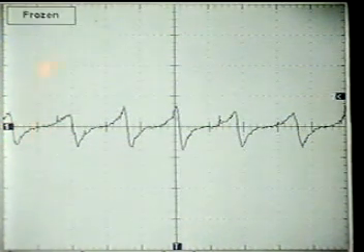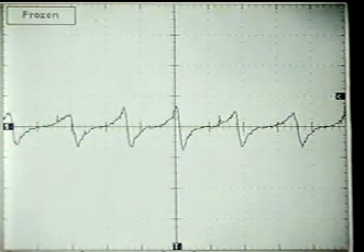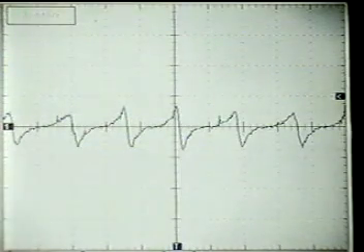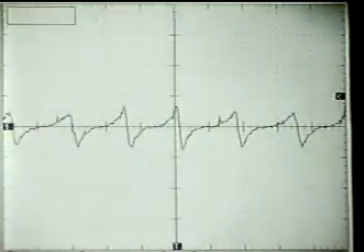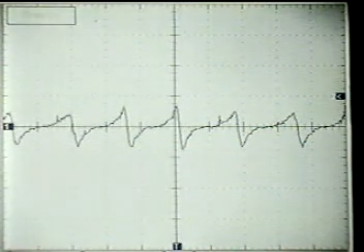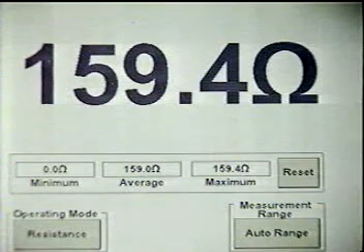What you're looking at on the scope screen, remember, if you reference your ground tick mark, the voltage that goes above ground is a positive slope, and a voltage that goes below ground is a negative slope. A peak-to-peak voltage would require us to add the positive slope and a negative slope together. Remember, we wanted a minimum peak-to-peak voltage of 1 volt. As you can see, we're short of that, so we're suspecting a weak pickup coil. You can see the ohmic check of this pickup coil shows it to be perfectly good.